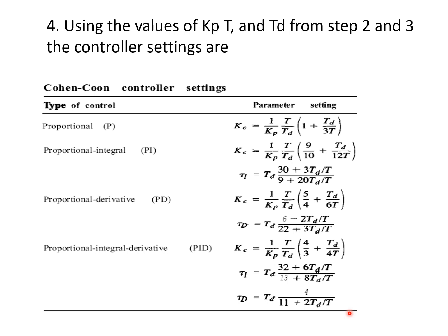For Cohen-Coon, you need to get the sigmoidal process reaction curve response. Most of the time you get it, but not all the time. Some systems are fast, and it may be difficult. Most of the time we noticed sigmoidal responses in slow, multi-capacity systems. But according to what they found, most systems behave like that when you run the system as designed. So these are the two basic controller settings that we can use.